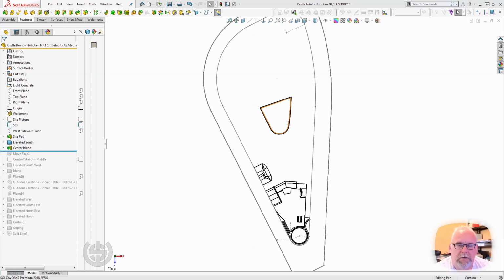Is the concrete good? The guys that were doing it, did they put gravel behind an area that's wet? In the Northwest, some of the parks have problems with seep, where moisture will come through from the back. They didn't put enough gravel down to get the water to drop behind the park. They did shotcrete right against the bank, and it heaves and bleeds through, and some of the parks are thin, or they didn't anchor the coping very well.